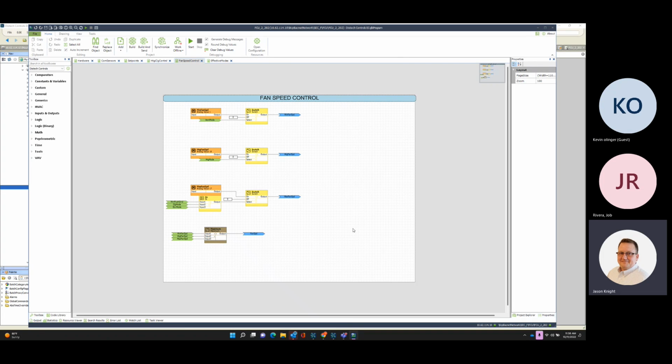Depending on the manufacturer and the style of the motor, whether it's GBM, Pabst, or whoever they're buying the motor from, you can get a 28 to 50 page troubleshooting guide for the motor module. And that's if the module's built in exterior on the motor body itself, or if you have to just replace the entire motor like a GBM Pabst motor. There is no module to replace. You buy a $2,000 motor.